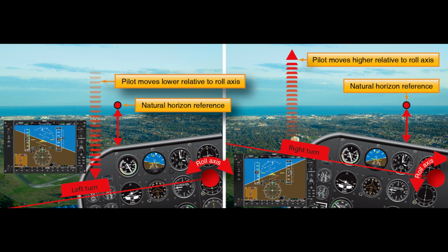In any case, the pilot should retain the proper sight picture of the nose following the horizon, whether up, down, left, or right, and isolate undesired motion. Common errors in level turns are: 1. Failure to adequately clear in the direction of turn for aircraft traffic. 2. Gaining or losing altitude during the turn. 3. Not holding the desired bank angle constant.